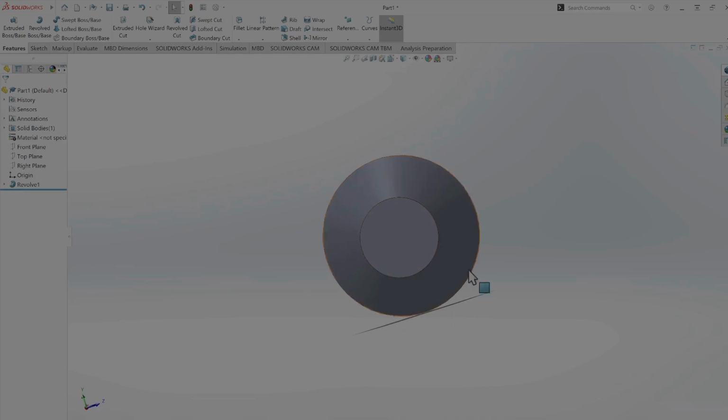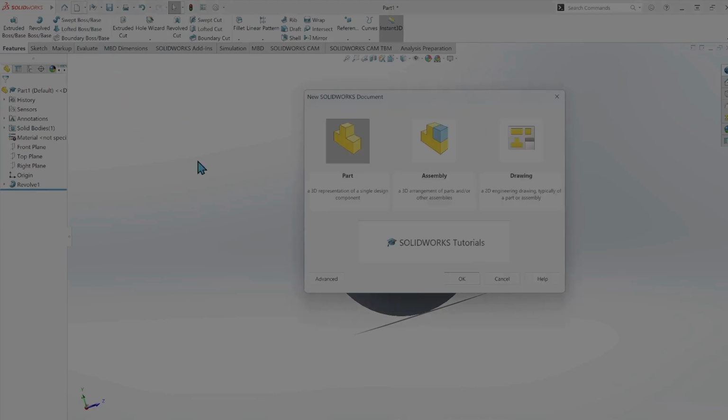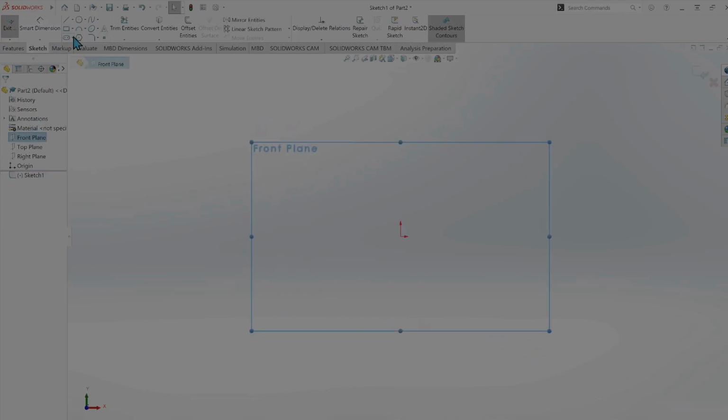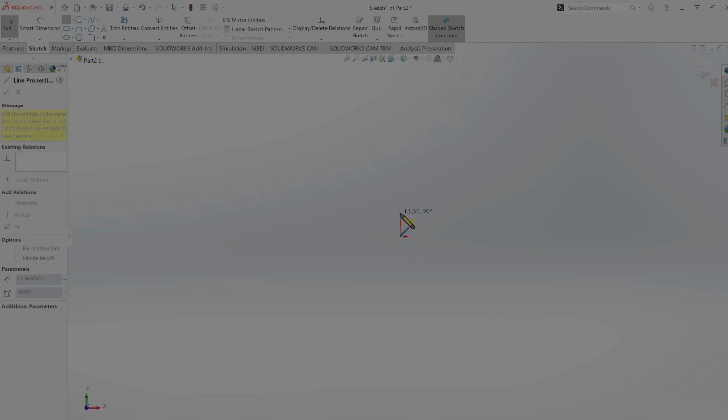I am making this sketch to explain the difference between first and third angle projection. The main difference is where the object sits relative to the viewer and the projection plane. So going back to the transparent box analogy, the projection plane would be the side of the box that you are viewing from.